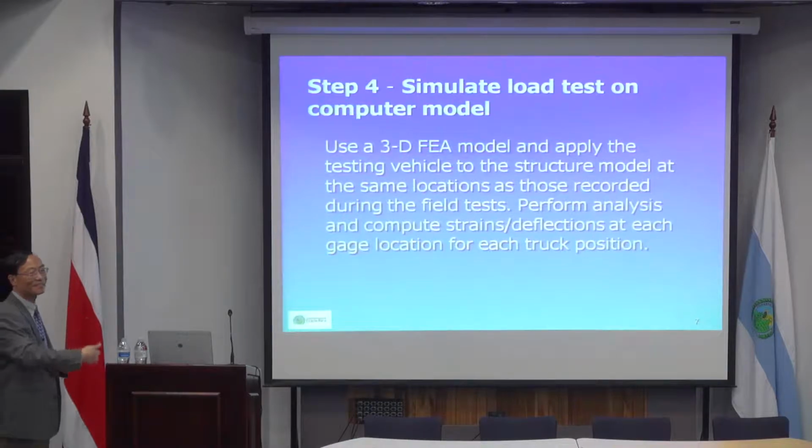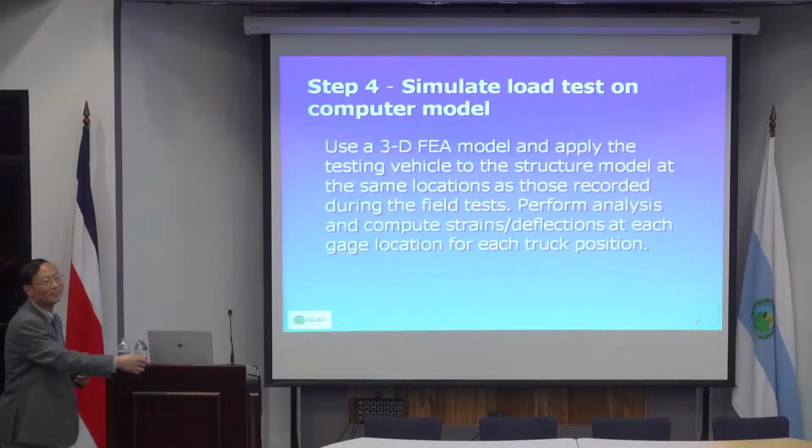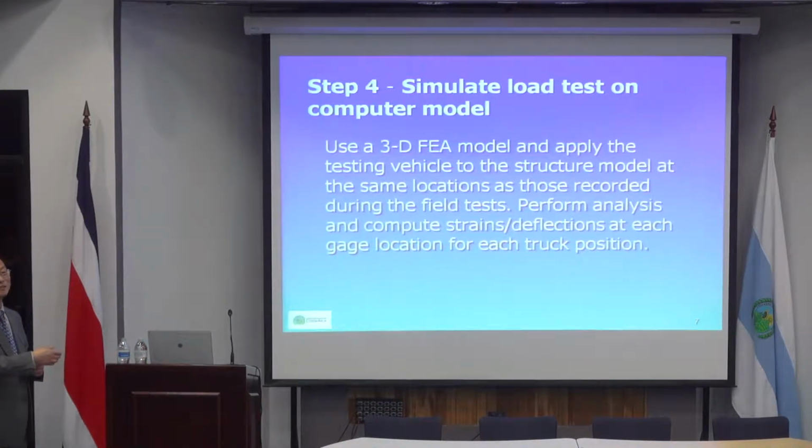Transversely, when you cut the deck into small pieces, you lose a major component of rigidity, which is the deck's ability to twist. Once you cut it off, it's almost like a timber deck. You cannot twist it. So that's why you can change the characteristics of these members in any way to represent the reality of the deflection or stresses.